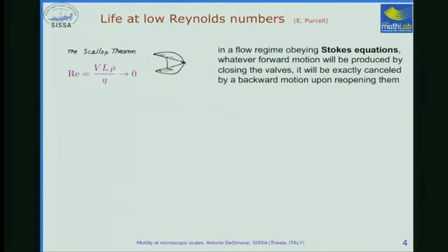The Reynolds number tells you that, and you are led to neglect inertia completely and to use Stokes as the right equations, and you change the framework of your equations. The equation of motion is no longer F equals ma, but F equals 0. Okay, so let's look at the consequences of that. Maybe I should say, there are many people in geometric mechanics in the program, but I don't see them in the audience. So, okay, I will say these things nevertheless. Very easy for them, not very easy for me.